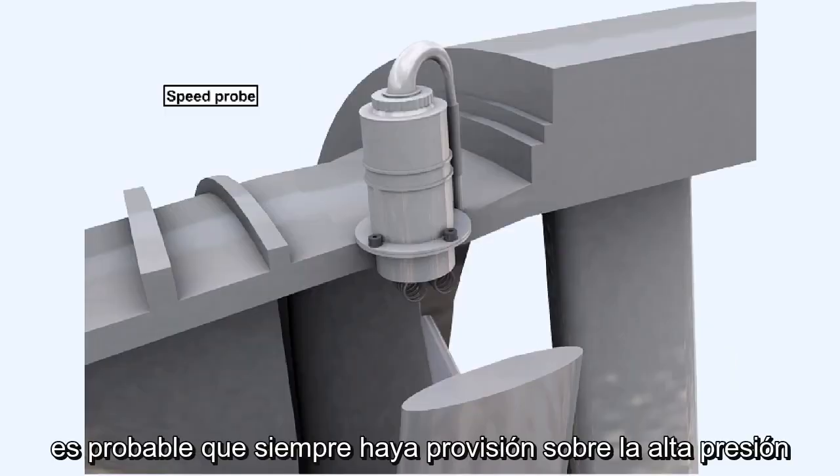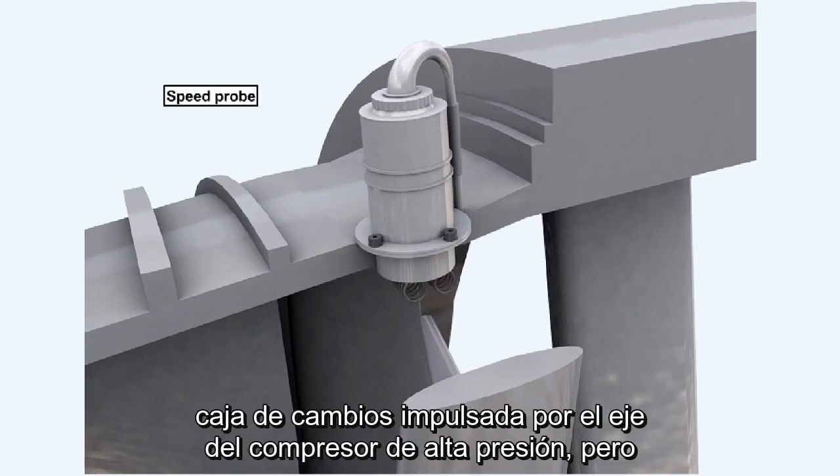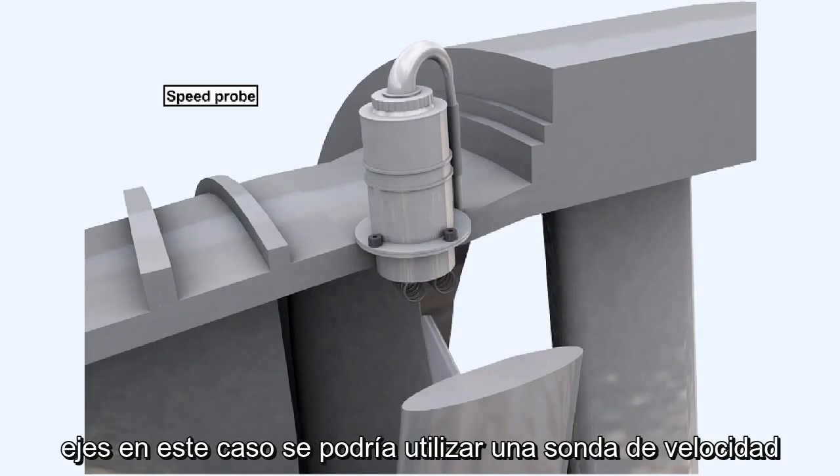It's probable that there would always be provision on the high-pressure compressor spool for driving a tachogenerator through the external gearbox, which is driven by the high-pressure compressor shaft. But it may not always be possible to have gearboxes driven by the other compressor shafts. In this case, a speed probe could be used.